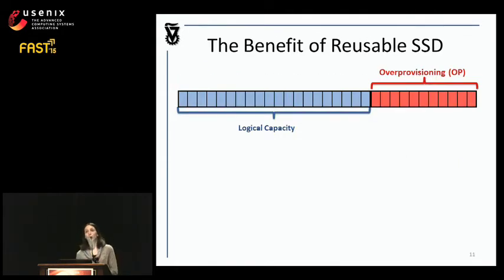Okay, so there is some overhead here because the second writes occupy twice as much space as the first writes. However, notice that the first writes are written as usual. So we can use the over-provisioned space, which usually holds a lot of invalid data, and use it for storing some useful data with second writes. But we don't need to increase the capacity of the SSD, right? We have now more place to store more data.